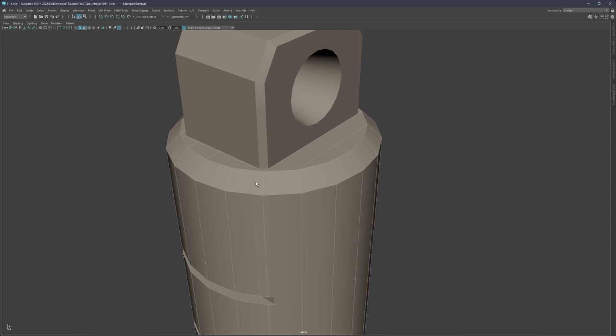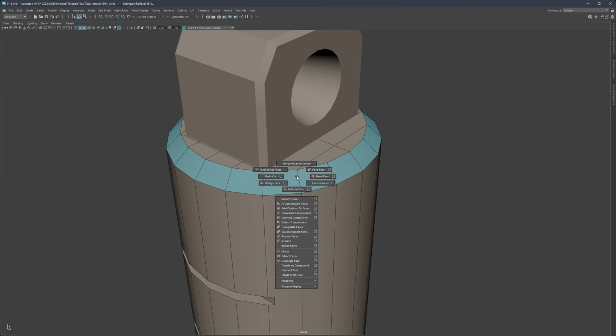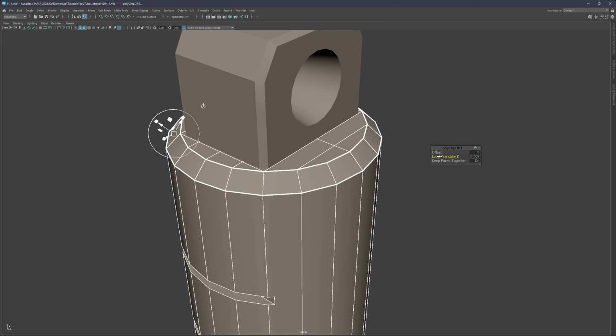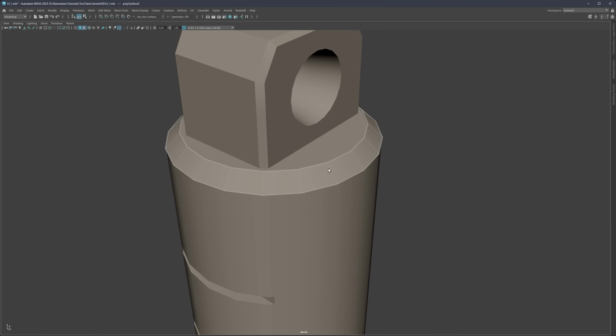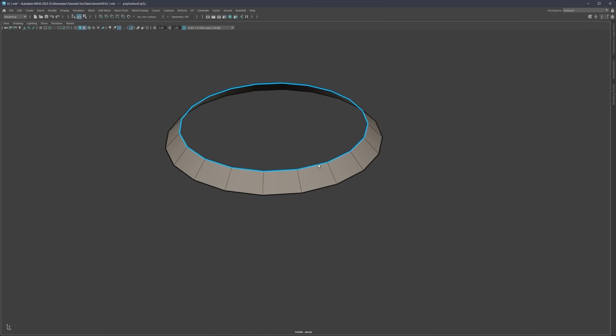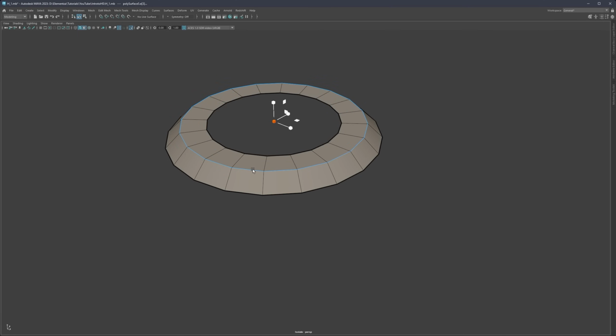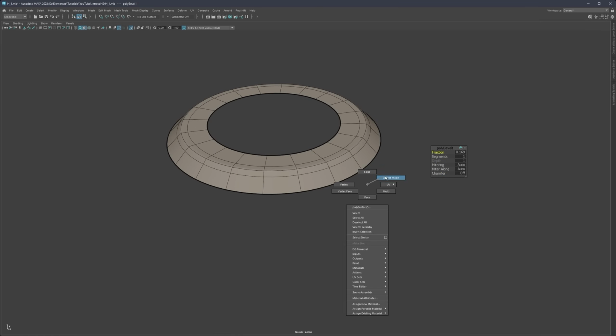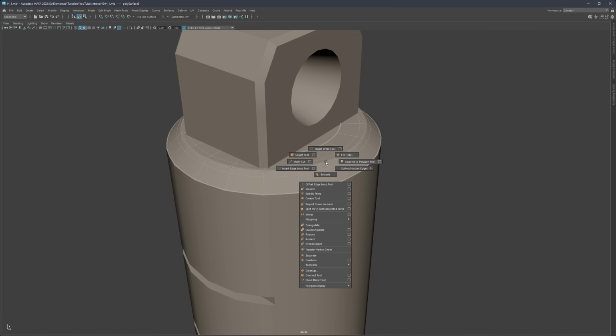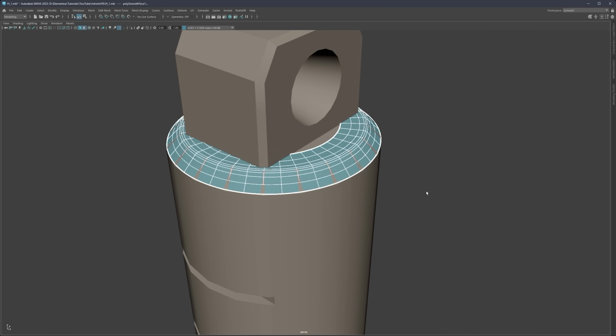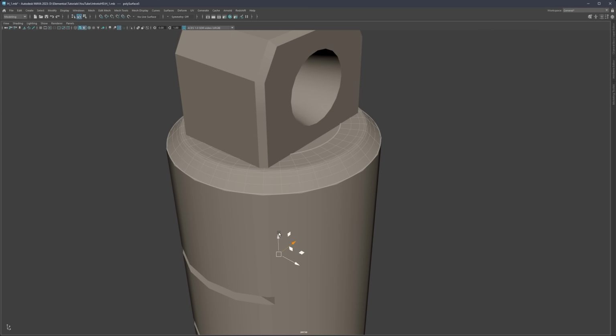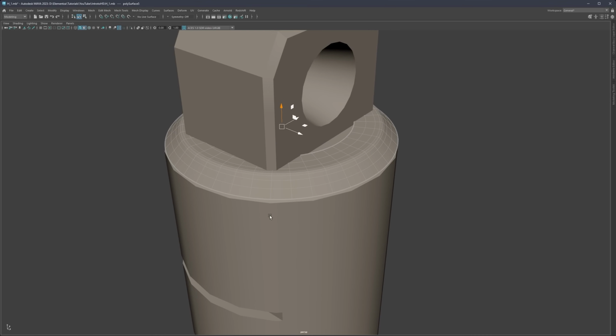So if you want to play it perfectly safe, we can select these parts. Let's go to duplicate face, so now we're going a bit faster here. Let's press Control 1 to isolate this, go to edge mode, and I'm going to hit scale and just extrude it on the inside. Because what I'm trying to do here, let me do a quick bevel, we are basically trying to simulate exactly the same thing. We are just going to smooth this real quick, just to see will we have enough topology to hold this corner. So this was, let's say, 20 subdivisions, and this is now 40 subdivisions.